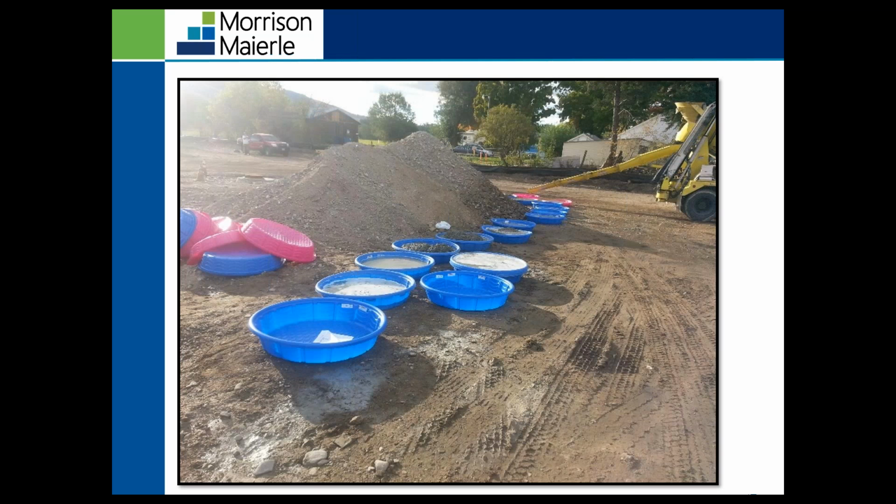This BMP right here, these are concrete washouts. For this contractor right here, they use kiddie pools as a way to contain concrete waste material. Really, when we're using these concrete washouts for a construction site, the truck driver, after they are pouring the concrete, needs to wash out the chutes. That's really what we're trying to contain right there, is that wash water from the truck. That wash water contains contaminants from the concrete that can then enter our aquifer and pollute our state waters that way.